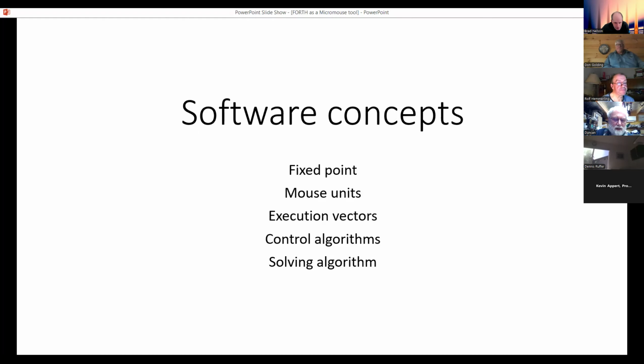Now for some of the ideas used in my code. The Forth I use is 32 bits wide. The ADCs are 12-bit. The PWMs are usually 10 bits wide as a good trade-off between speed and resolution. So my inputs are from ADCs and odometry counts. They're all fixed point and not very many bits, no more than about 16. My outputs are PWM numbers to control the motors, and for those 10 bits is sufficient. All my arithmetic is in 32 bits. So there's absolutely no need for floating point. So I don't. Lots of mouse builders do though, and they get mixed results.